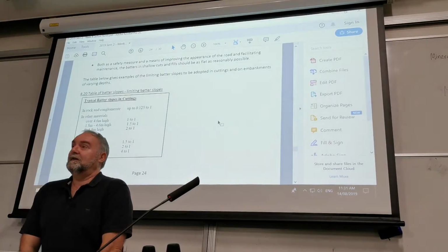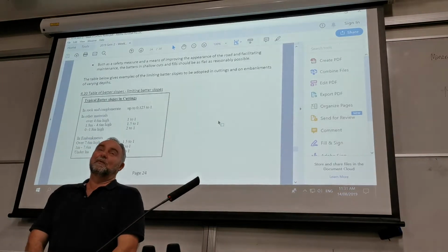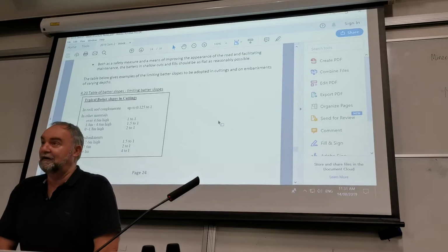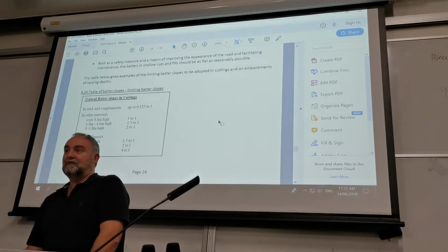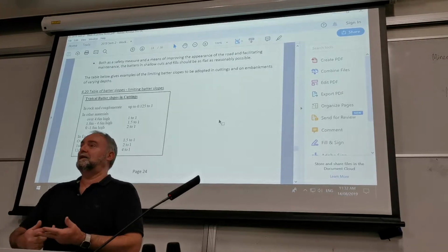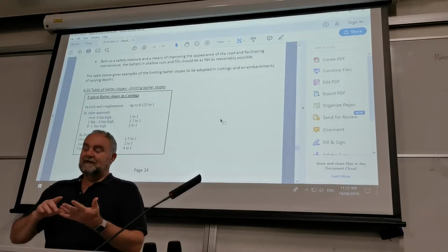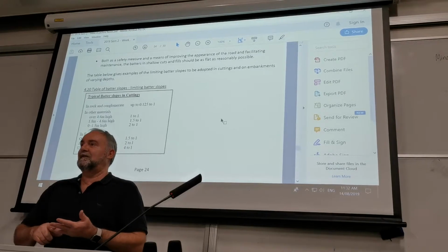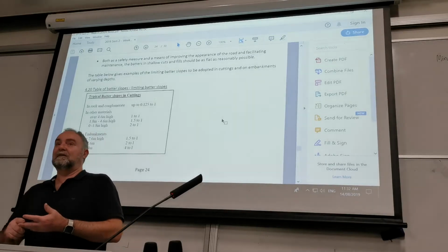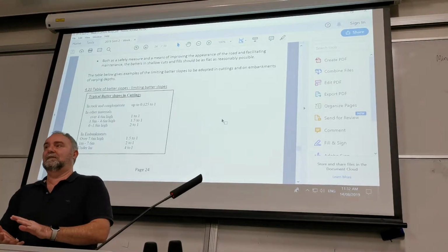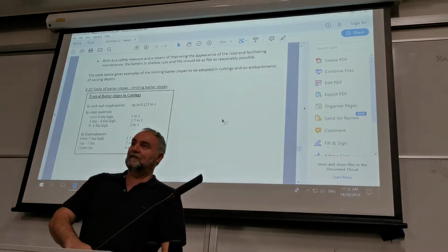A job like here at Unitech, and here's another note for you guys as well. You're talking about wetlands, you're talking about the water being very sacred to the Maoris, or the local iwi, sorry. So with that in mind, bringing anything extra onto site, it would have to be washed, clean and proper engineering fill, approved by everybody, right? So you'd need to tick in the box from the Greens, you'd need to tick in the box from the iwi, you'd need to tick in the box from an engineer on site to make sure it can be properly compacted. So you can't just take some fill, bit of old concrete and tube or whatever it's in someone's backyard and throw it in there.